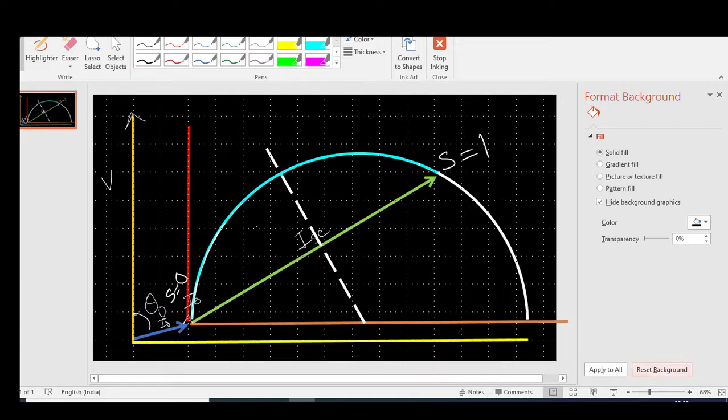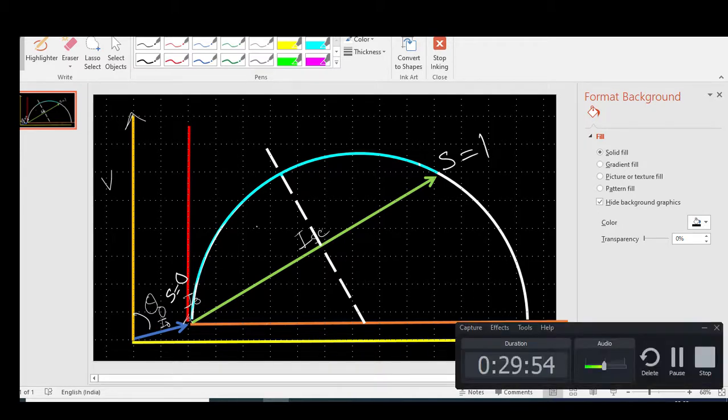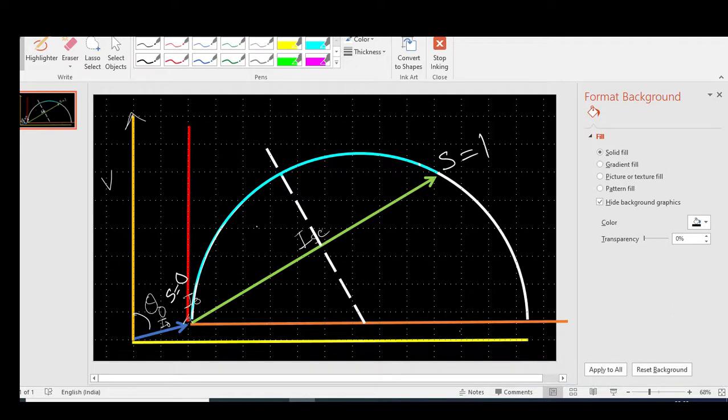Now see here, once we construct this circle, there are a few more things we need to be careful about. I'm going to make two claims. If the circle diagram for a machine is given, then we can figure out its torque profile and everything for a given power. So this circle diagram is complete and it reveals all about your induction machine.